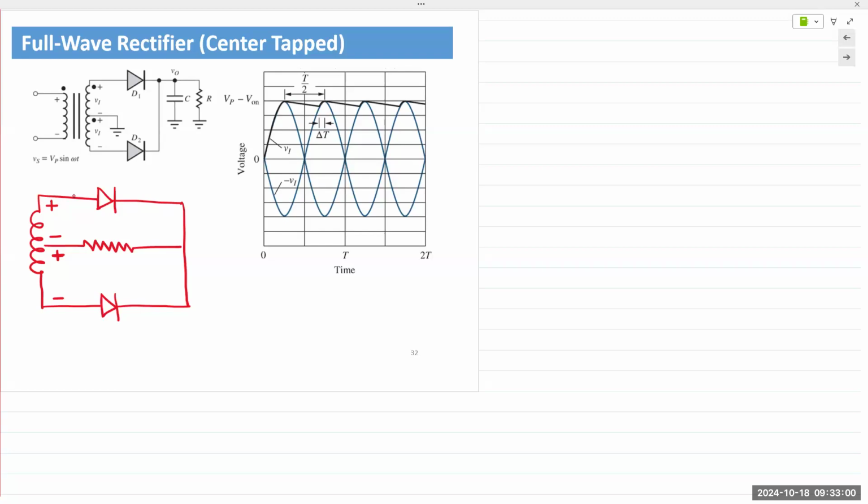Okay, so center tap transformers. The tapping simply allows us to choose a voltage at a desired level. Center tap meaning approximately in the center of the secondary coil, so it's equal halves of the secondary coil. So if we wish to have a voltage of 12 volts at the output, then we need to have a 24-volt transformer tapped in the center, so each half would give us 12 volts. Does that make sense? Right?